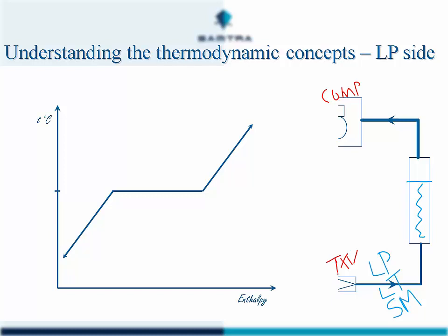Heat energy from the cold room is still being applied to the refrigerant. And this heat energy, we have a fan, and the fan is passing the air around the cold space and passing it through the evaporator. So the heat energy from the cold room is being absorbed into the refrigerant in the evaporator. Okay.